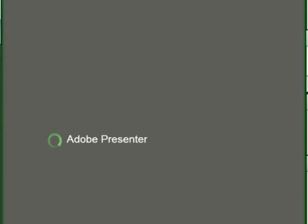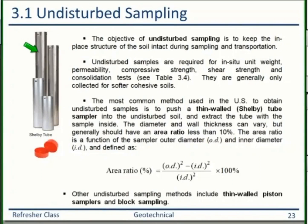Okay, chapter 3 talks about soil sampling. To understand the behavior of soil, and to understand the parameters to be used for the designs, we need to do lab testing. For lab testing, we'll need soil samples. There are two techniques to obtain samples. One technique is undisturbed samples, because sometimes you will need an undisturbed sample, sometimes you could use a disturbed sample. An undisturbed sample, as defined, is a sample which keeps the in situ structure of the soil intact.